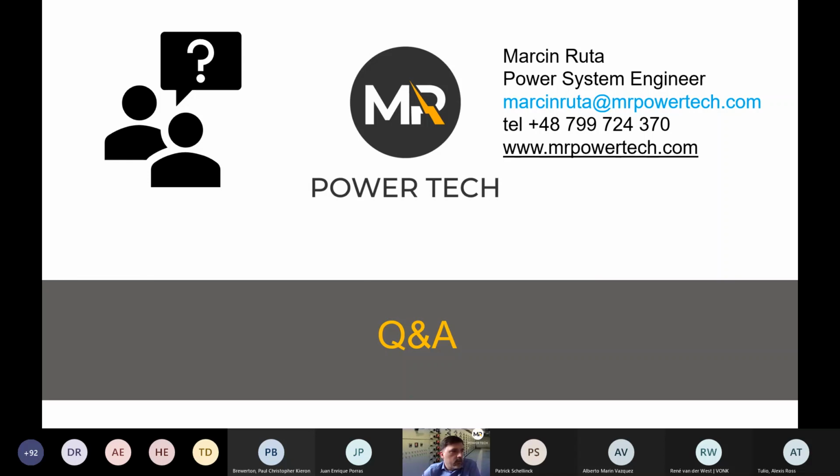What is the digital tool approach here: SKM, EasyPower, ETAP? Since I work mainly in Europe, I might say that the best is to use IEC 60909 for all the short circuit calculations, because that's the world standard, and most of the software will allow you to do it. I know SKM will allow you to do it, and ETAP also. If you did it with IEEE ANSI standards, then it's probably good to rerun it, because you will see some differences. So generally, I align all the IEEE calculations to the IEC world.